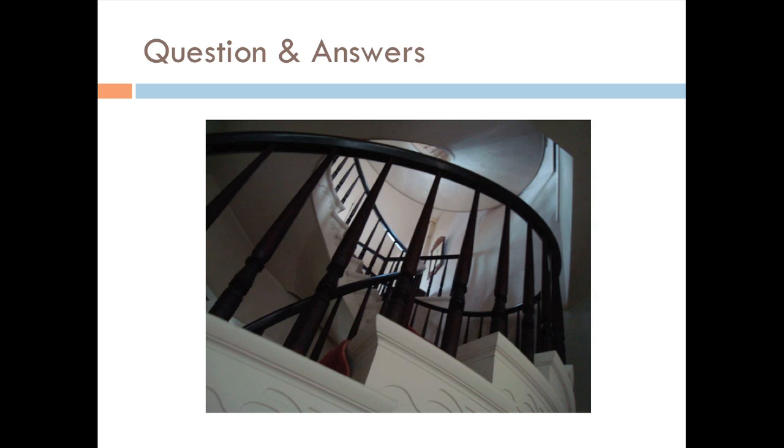My only reason why I wouldn't say, why not use a Portland cement base, is because if you're covering those walls, they can be pretty long, pretty big, square footage wise, and there I'd be worried about cracking. And if a crack were to open up, that gives a place for water to find its way in directly. I agree, but a lot of times if water's in there, that crack will present itself because water is in the wall. So I spent my whole life trying to keep the water out of the wall.